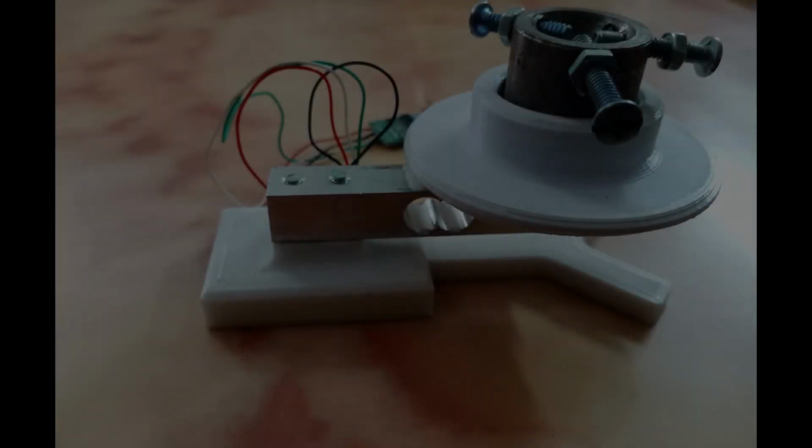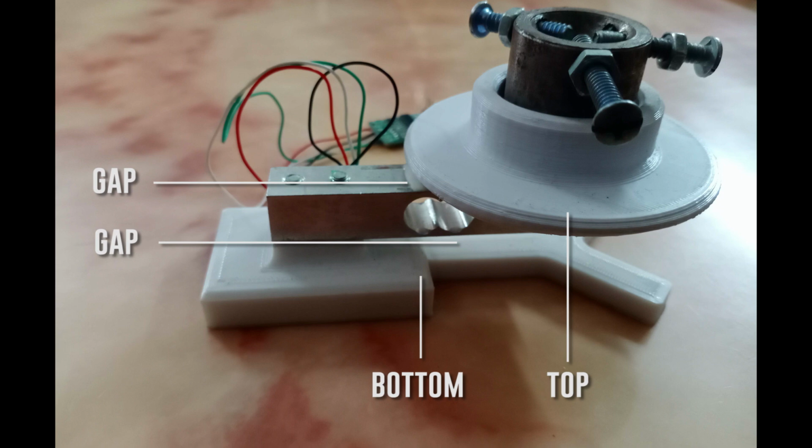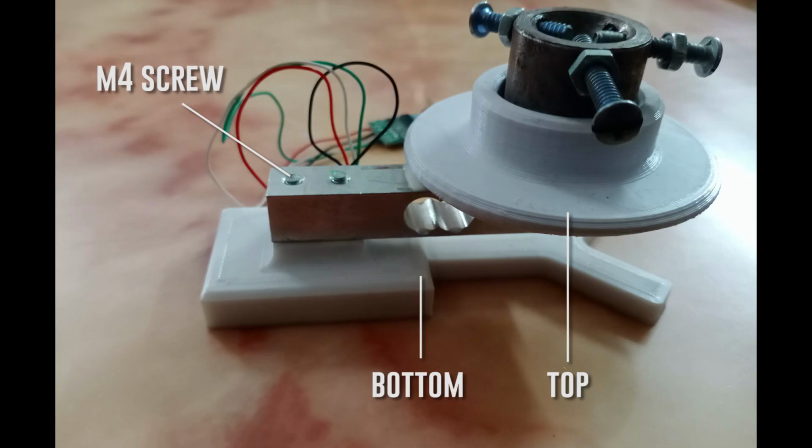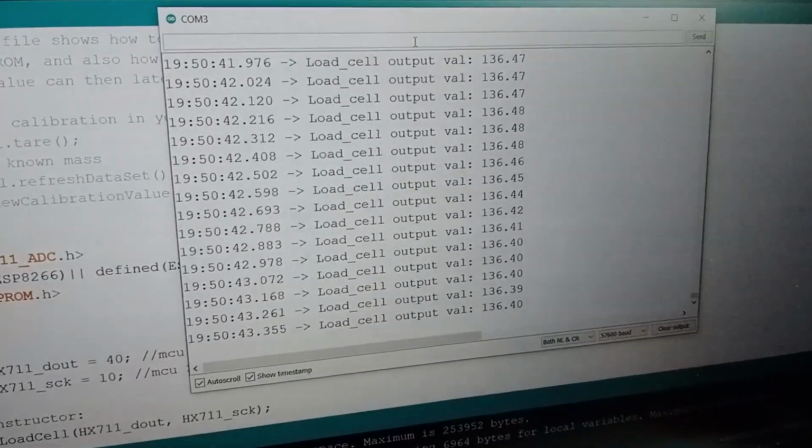Also, we 3D printed these two parts to mount the load cell. Load cell works by strain gauges which need space to deform, so it should be kept in mind when designing these parts. M4 screws were used to join the 3D part and load cells together. We used HX711 library to calibrate and get data from load cell to Arduino.